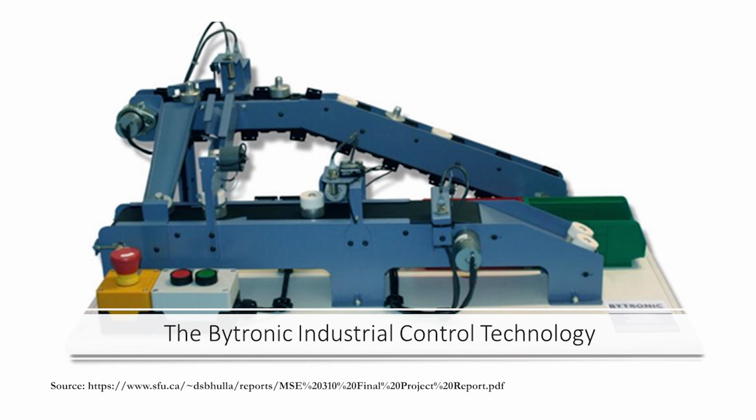That is because this capacitive sensor reading will have a reading that crosses a threshold. Once it crosses a threshold, then, based on the circuit here, it might be that the assembly has taken place correctly. So, in that case it lets it through. If it does not cross the threshold, and it is between two values which indicates that it is just a peg or just a disc with a hole, then it will kick it into the red box.